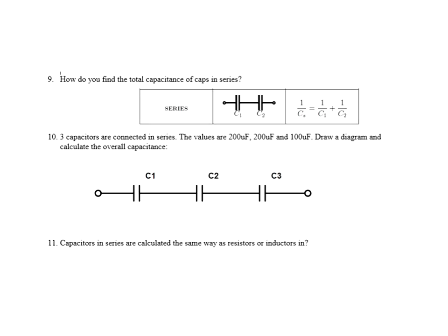Now, how do you find capacitors in series, though? Well, capacitors in series are found the same way as resistors in parallel. So you need to use the reciprocal formula. Here's an example right here. I have two capacitors in series, C1 and C2. I take the reciprocal of C1 and add it to the reciprocal of C2. Make sure I hit the equal sign and hit the reciprocal key. You know the reciprocal key on your calculator.